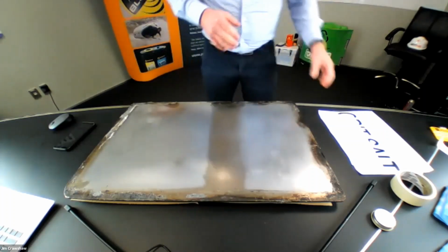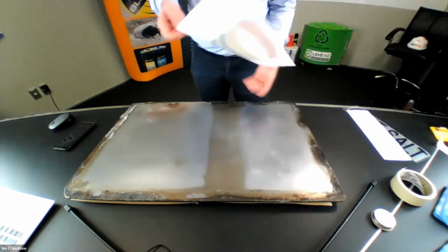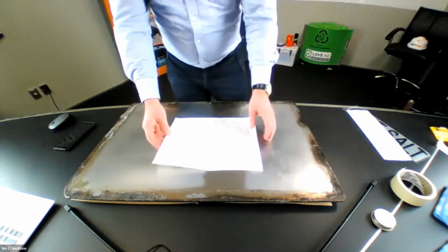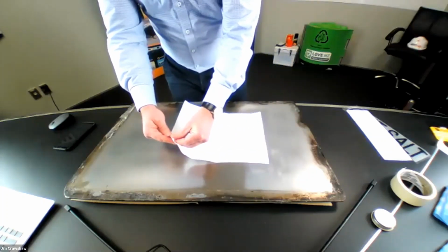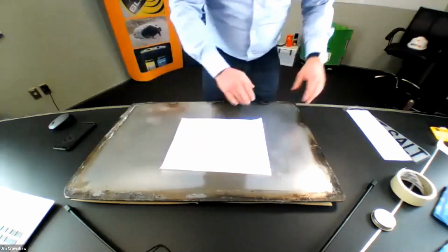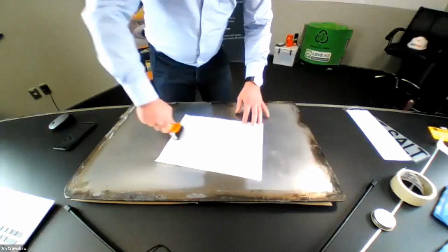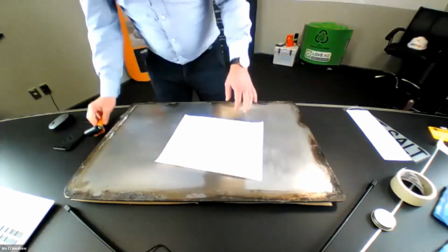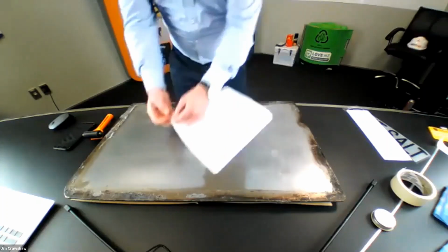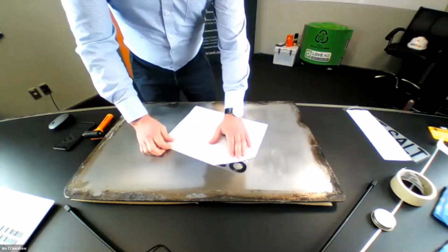Okay, next up, I'm going to run through the graphic applications for you. Starting off with the type 2 INMOULD original. This is the type where we talked about not peeling the tape straight up, but flipping it over this way. So I'm going to give it a quick roll for a start. I'm rolling over this tape because, especially if it's been in storage for a long time, that tape can tend to separate from the graphics. It's just strong enough to hold it in place while we transfer it onto the mold.